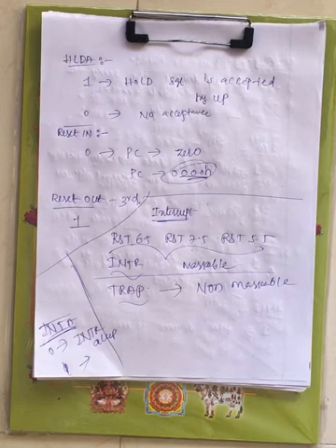Interrupt is nothing but stopping the process of a microprocessor. If a user wants to stop the process, the user has to give an interrupt signal. There are five different types of interrupt signals in the 8085: RST 6.5, 7.5, 5.5, INTR and trap. 6.5, 7.5, 5.5 and INTR are maskable, which means once generated, we can disable them by giving some instruction.